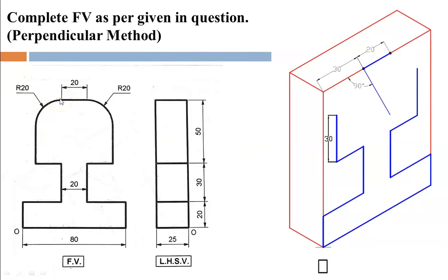Till now we have solved problems for the complete circle, or you can say a semicircular feature, where we used the 4 center method. But here there is no need to go with the 4 center method, as it is time consuming considering a quarter circle, because we need to draw only one arc, so one center is required.